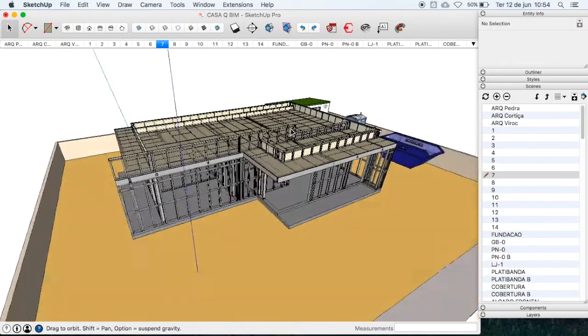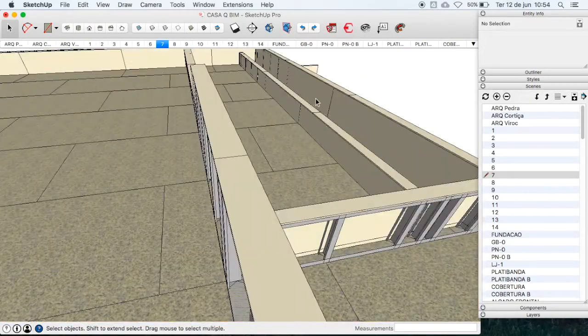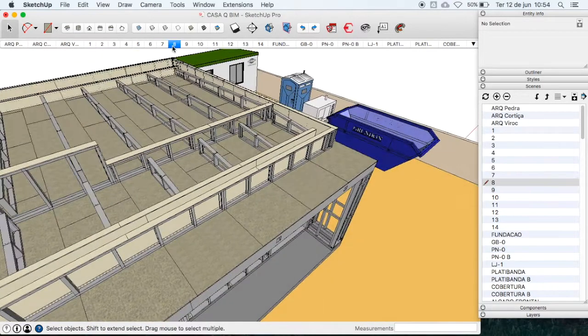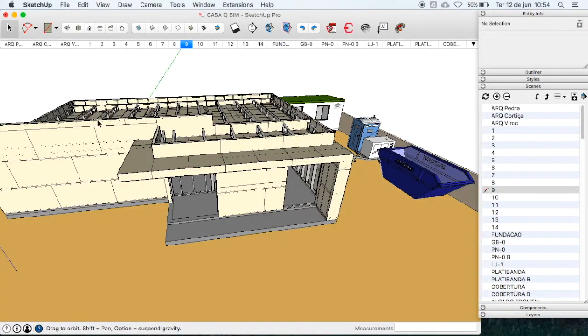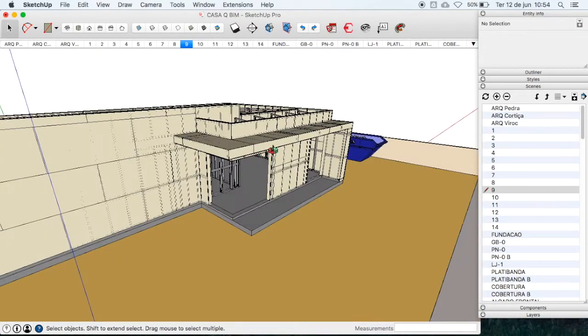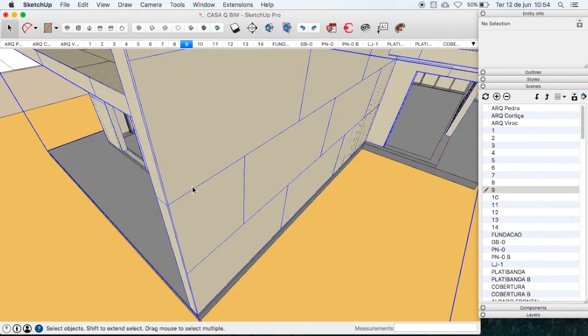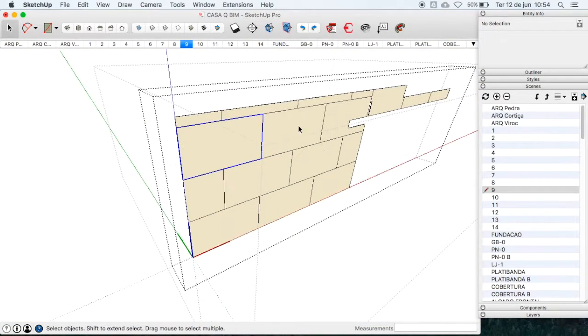Objects are grouped according to the actual construction scheduling. For this reason, you can see that the inner lining of the walls is in a different group than the outer lining of the walls. This happened because the inner lining has to happen before the installation of roof panels. This is a small example that shows how 4D BIM can be useful to avoid errors in the construction planning.